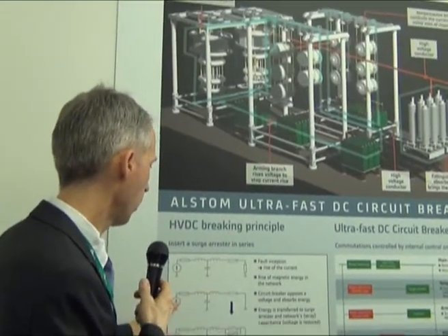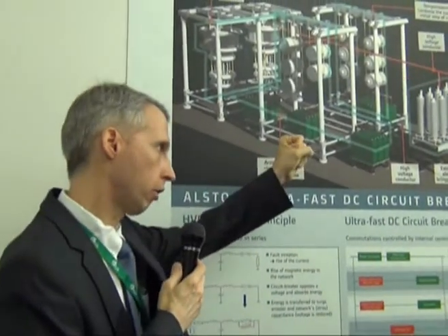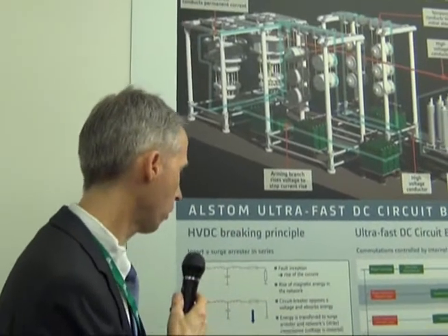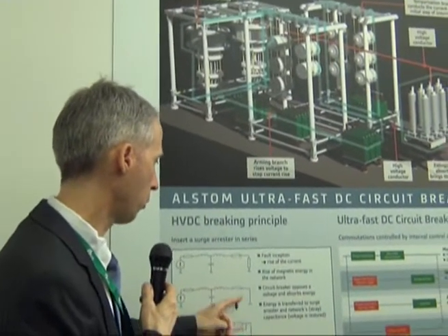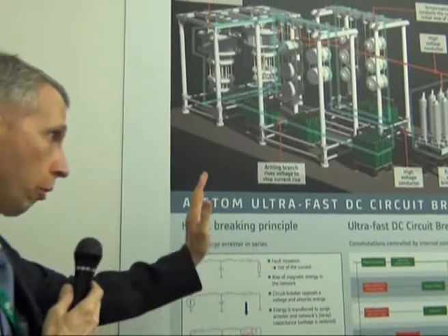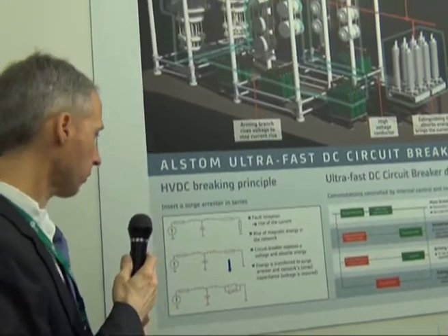As we were saying earlier, the current keeps rising and you have to catch the current during its rise and bring it down somehow. This is done by our circuit breaker, who inserts an element that opposes a voltage that is higher than this one, which acts sort of like a brake.